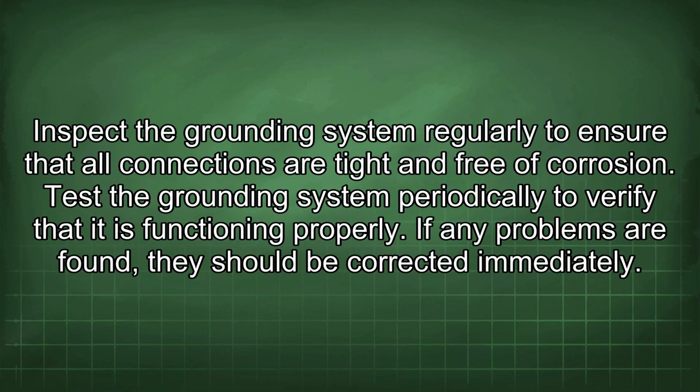Inspect the grounding system regularly to ensure that all connections are tight and free of corrosion. Test the grounding system periodically to verify that it is functioning properly. If any problems are found, they should be corrected immediately.